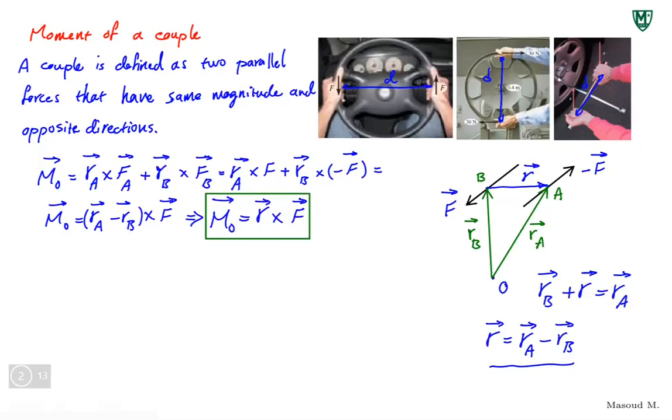Interesting, right? So it's a free vector, can be anywhere. As long as these two forces move together wherever they go, the position of this couple does not matter with respect to some point. What matters is the position of these two forces with respect to each other. As long as they're parallel and the distance is the same, the moment of the couple is the same. So it can go anywhere in this space. So I can even get rid of this O there, and I say this is just the moment of this couple. It has nothing to do with the point I'm finding the moment about. So let me just write it here. So M, to emphasize, is what I would call a free vector. Rotation. It can act at any point. It only depends on F and the distance between those two forces.